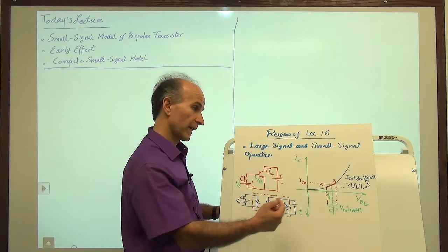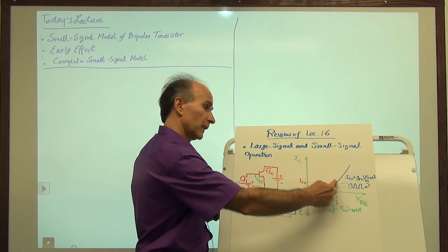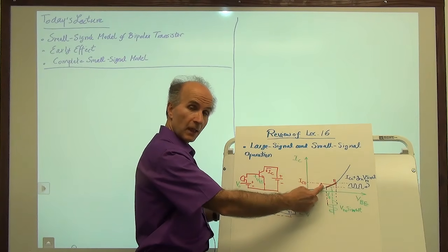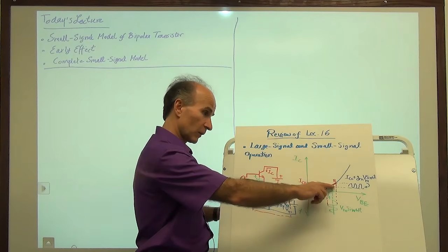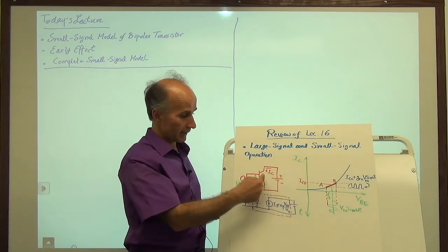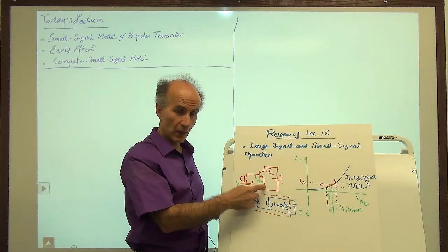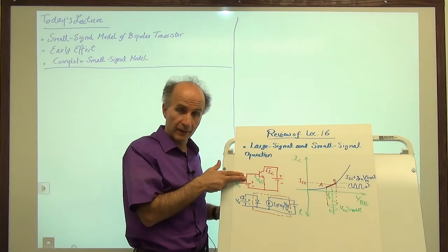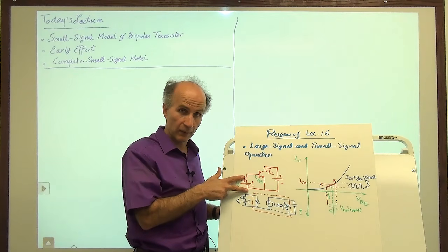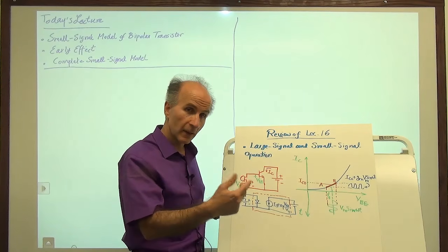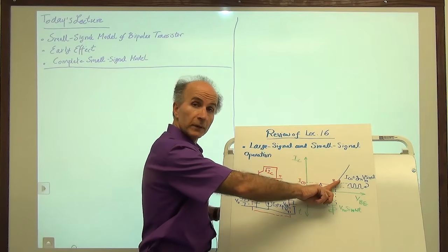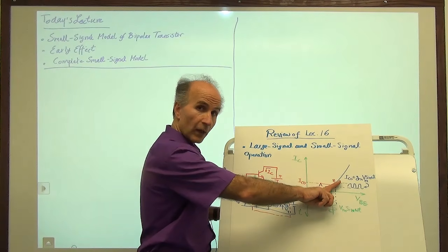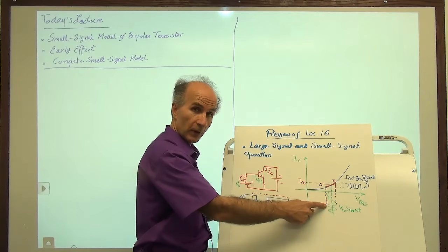And what we saw was that the total current that we observe in this regime is equal to the bias current, which we called IC0. That's the current flowing through the transistor when there is no signal, just due to the bias voltage, plus a fluctuation, which is given by the slope, which is gm, times the input voltage fluctuation.